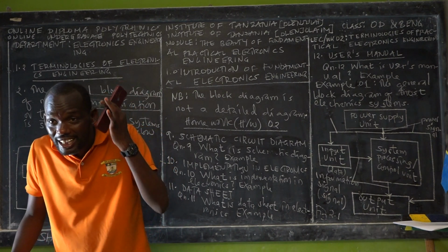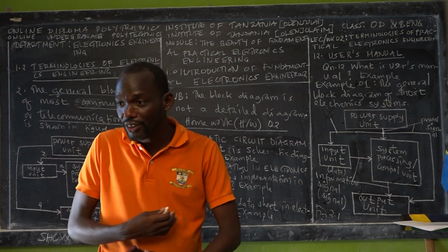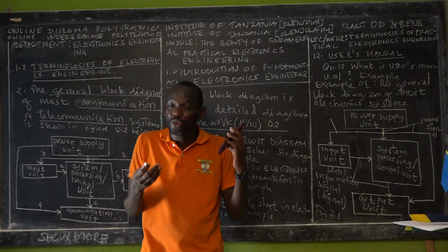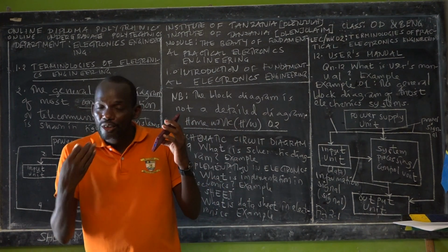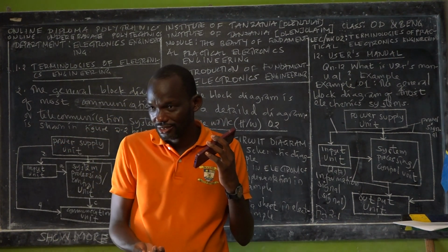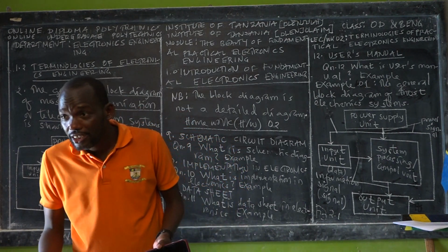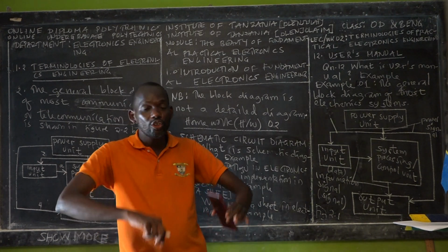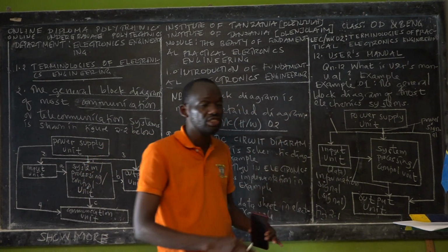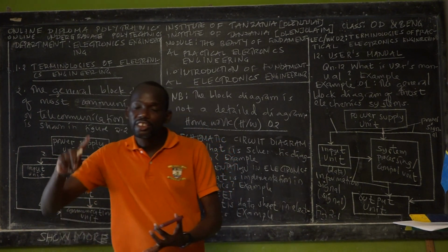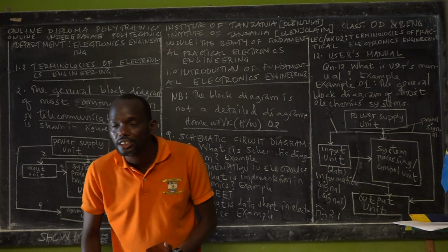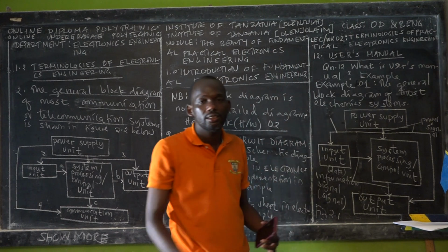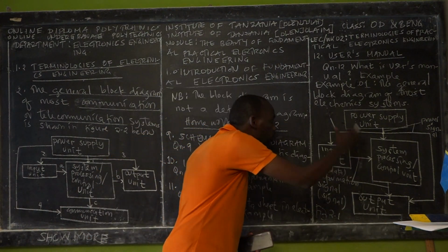Once you talk with your father, or your children, there's a surface mounting microphone picking up your voice. So the microphone, the video camera, and the keypad, all of them we categorize into the input unit. The battery, the charging IC, integrated circuit, voltage regulators and so on, we categorize in the power supply block.